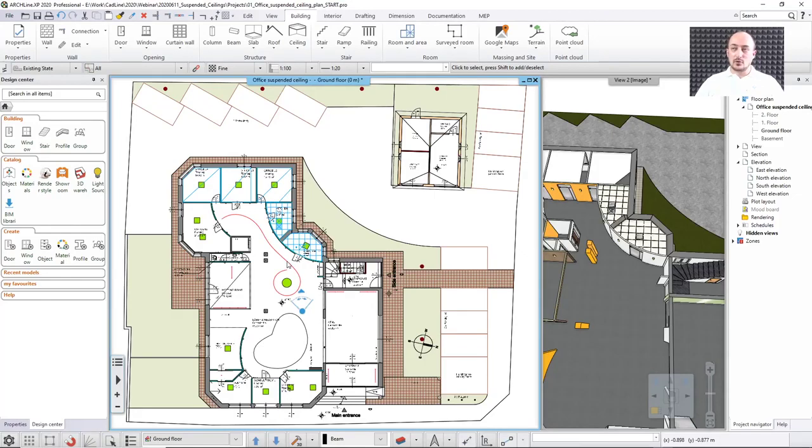So these are the two main manual placements: when you either choose a room and you place it automatically filling the whole room, or you use a polygonal contour that you just pick point by point or any other ways that appear at the top here in the ribbon during the drafting, and then you can reshape it later on as well. So now let me just undo this, because I will actually go with another option.